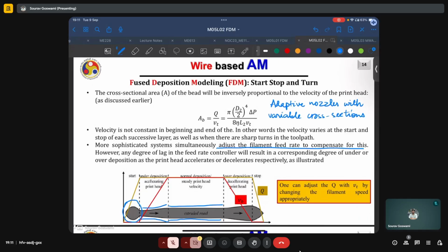Because previously we have discussed how for the perimeter pass, the deposition has to be very precise. And so typically this is performed either at a slower scanning speed or if possible with say a laser or energy beam of a smaller diameter to have more control over the process.